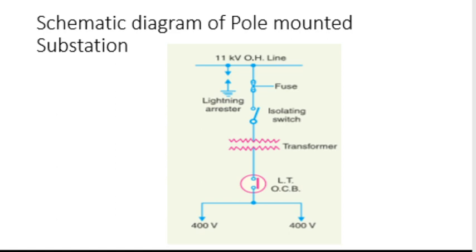It shows an open circuit for the 50 hertz regular voltage supply, that is 11 kV. But whenever there is a high voltage, the lightning arrestor comes into the picture and gives a path to that current, and it is all shunted through the lightning arrestor to the ground, so that all the other parts of the transformer are protected.